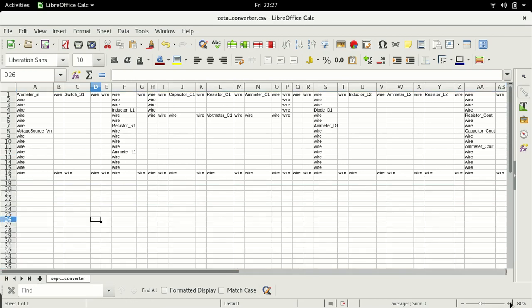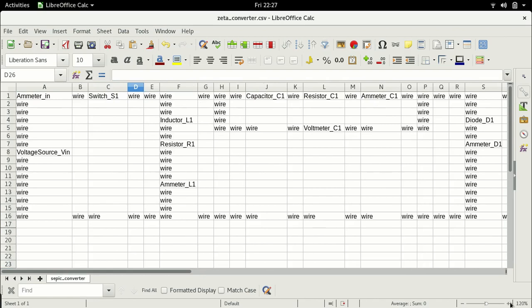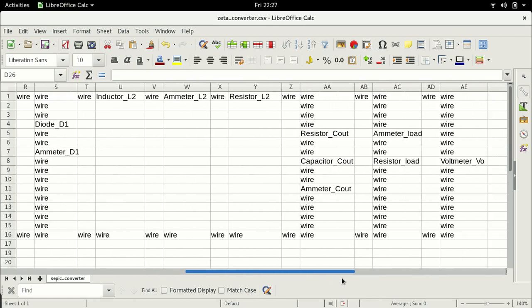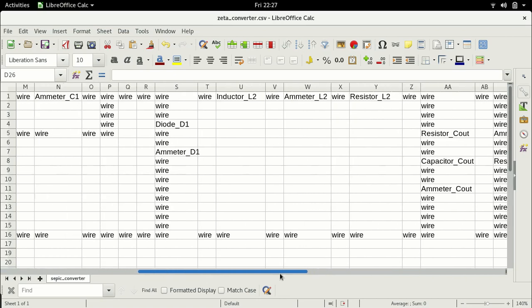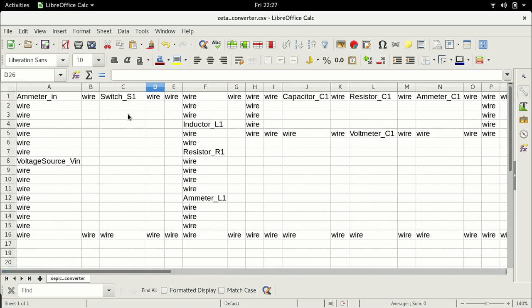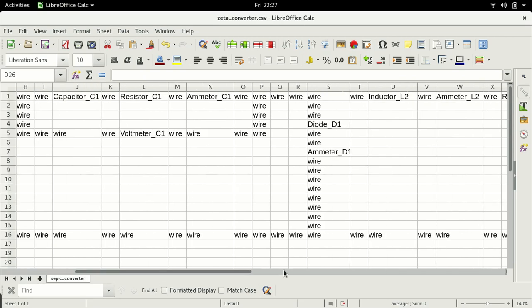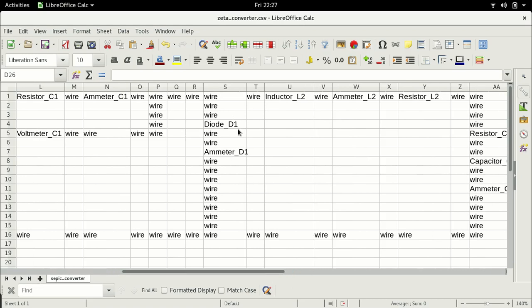So now that I'm done with this, let me just zoom in a little. This is where we were, right? And this is pretty much the circuit. The rest of it is almost the same. Only you see we've just switched the position of some of the elements, right? The inductor, which was in the series path, is now in the parallel path. The switch was in the parallel path, is now in the series path. The decoupling capacitor stays exactly where it is. The diode has switched with the inductor, and the diode has reversed in polarity.